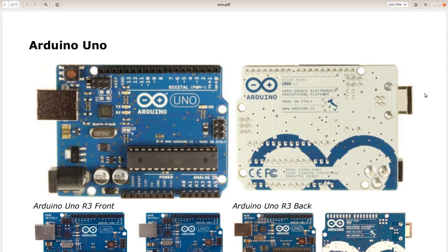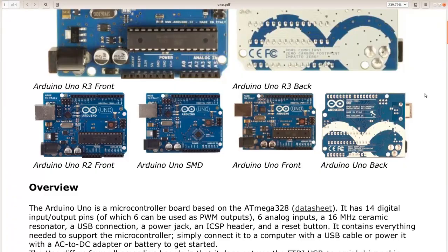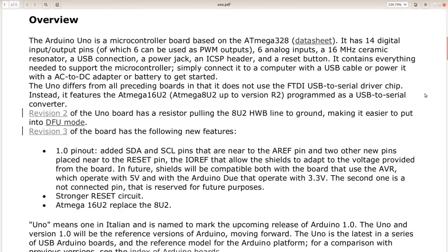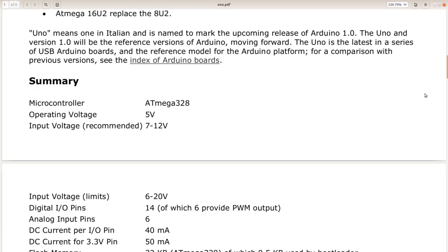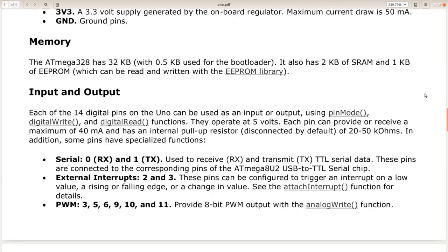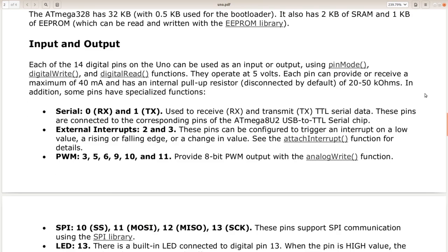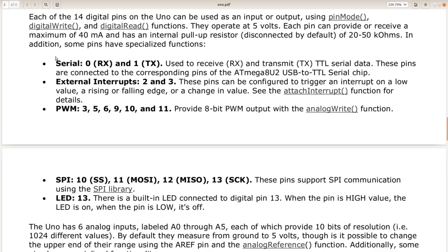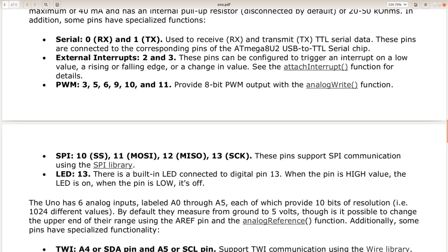As you scroll down, you can see highlights of some more important information, such as the external interrupt, which is the topic of the next video lecture. You find also information about the SPI, the Serial Peripheral Interface, and the 4 pins associated with it. For example, the Slave Select SS, the Master Output Slave Input MOSI, Master Input Slave Output MISO, and the Serial Clock used for serial communication. We will introduce these concepts in a future section when we use the Arduino as a serial programmer for an ATmega32 microcontroller.